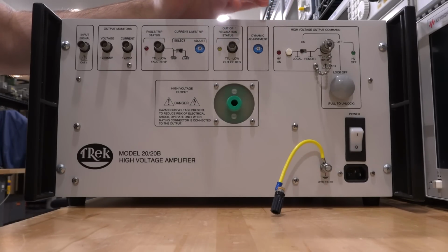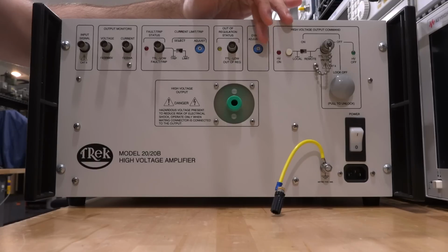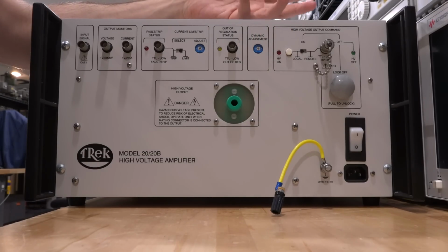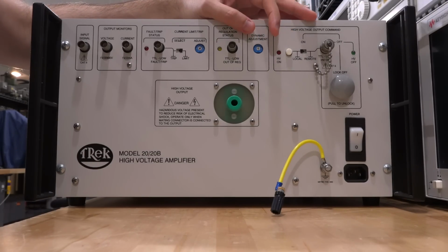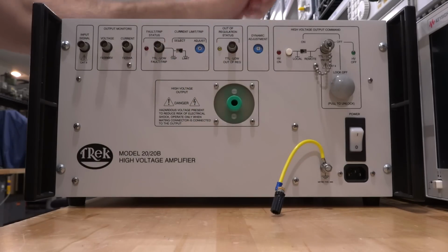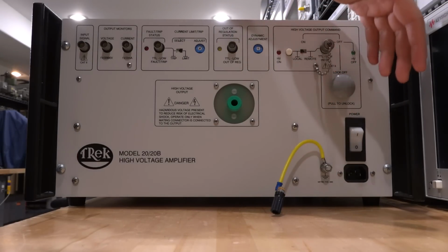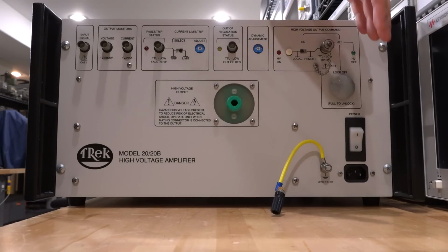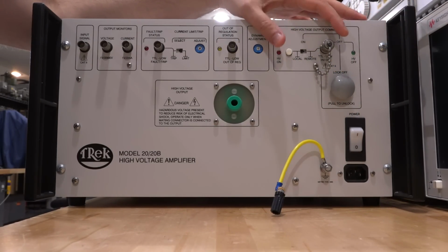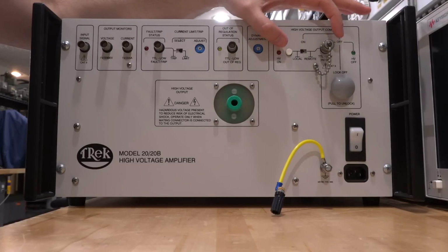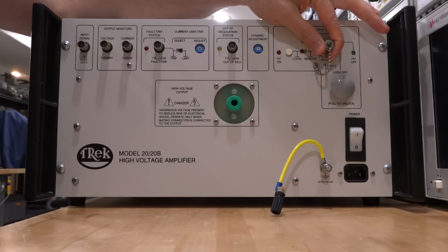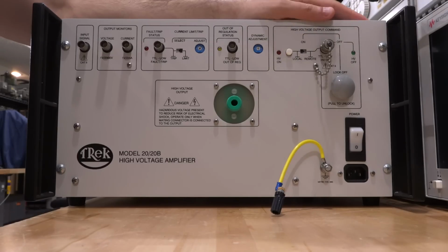And this is useful because it also works on AC. And there's a dynamic adjustment here, but it basically changes the AC response of the output driver in case you want to drive a capacitive load from this output over here. Other than that, it's pretty self-explanatory. We do have this thing that you pull out to enable, and then when you push it in, it cancels or disables the output, and you can have the output be cancelled or disabled by an interlock or just permanently connected, and then you just press this button and it enables the output.